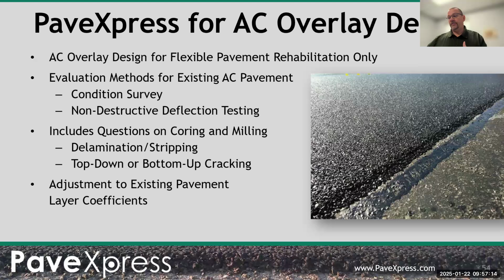Or if you're stabilizing the subgrade, then maybe you don't need as thick of a sand sub base or aggregate base over that. So there's a lot of considerations that go into that, and some of that's where you can play around and try to optimize your design. Yeah, the comment was sometimes we have 4 inches of clean sand below our existing aggregate, which is a very reasonable thickness for a sub base.